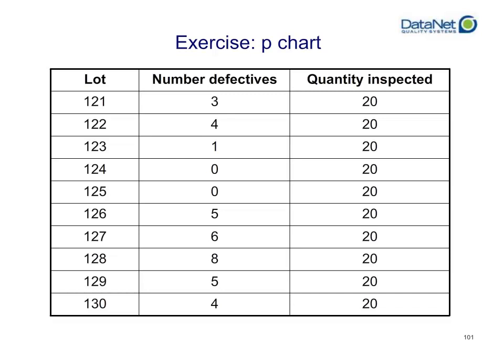It is very important if you want to use a P-chart that your lot size be exactly the same. There can't be any deviation in your lot size. If there is deviation in your lot size, you can no longer use a P-chart. You need to use one of the other chart types listed earlier on, and you're going to need to keep very close track of how many were actually inspected each time. You would have used an NP chart, or number P-chart, which gives you a count instead of a relative percentage, but that's beyond the scope of this particular exercise.